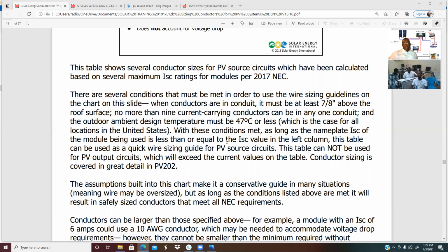So like Liberia, you have to put half of that number into the conduit because the temperature there is very high, and you want to avoid the heat. So if you have an 85 degree or 80-some degree, you can put only like 4 or 5 into a conduit.